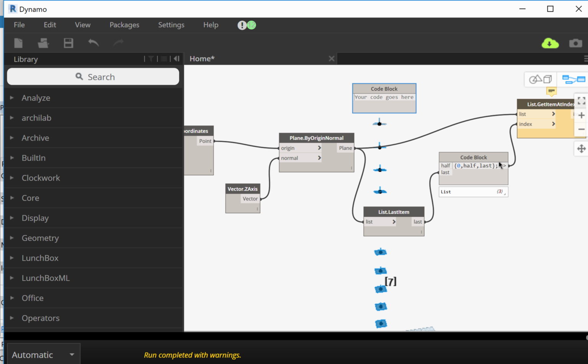and the easy thing to do is to do count. And notice this, in Dynamo, functions are explicit nodes. They could also be DesignScript functions. Like, for example, I don't have to add the Count node. I could also use the function. But rather than complicate this, I'll go easy with you. This is going to be C divided by 2. That's the count divided by 2, right?